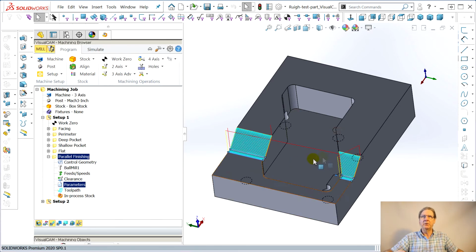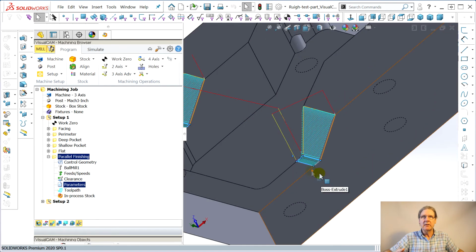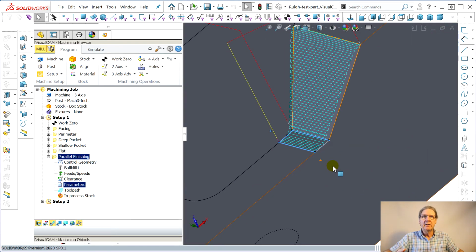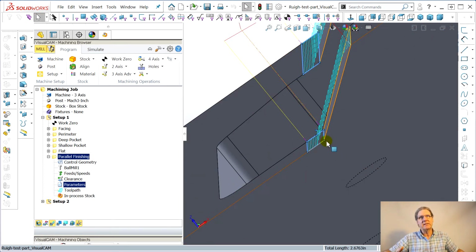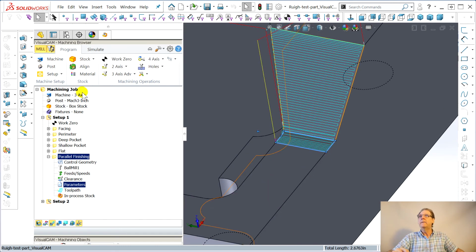Generate. Boom. And because we added those little sketches, see before, it does the math where it uses this line, goes straight up, and it won't let the tool, the center of that tool, go any further. So it leaves a big scallop here. By adding this little patch, and you could see it could be narrower, right? It runs the tool path all the way down till the theoretical end of the ball mill touches and makes this corner scallop much smaller.